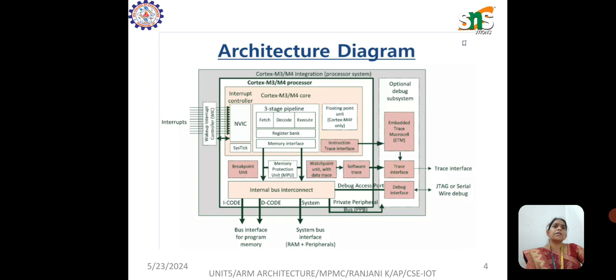And next is the incrementer for load and store operation instructions. The incrementer updates the content of the address register before the processor core reads or writes the next register. Next you have an address register. This holds the address generated by load and store instructions. Next you have an instruction decoder. It decodes the instruction opcode to read from the memory, and the instruction has to be executed. Next you have a register file, the bank of registers, which are 32-bit registers for storing the data.